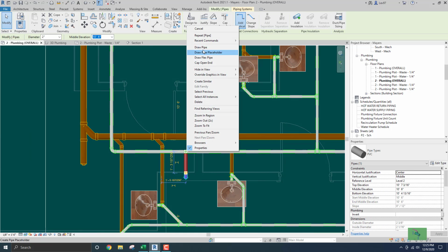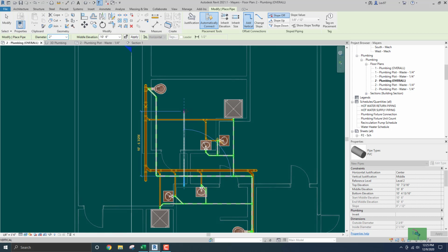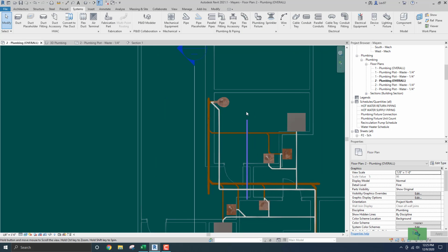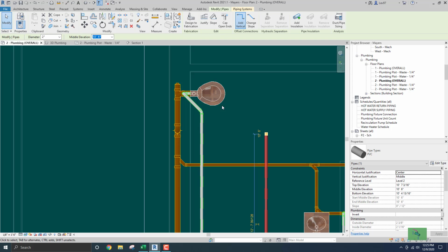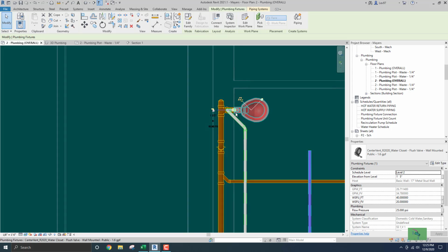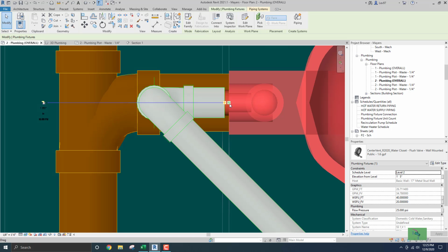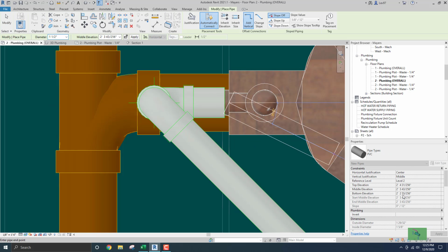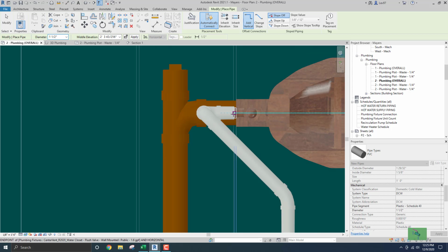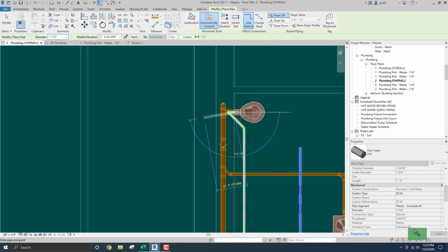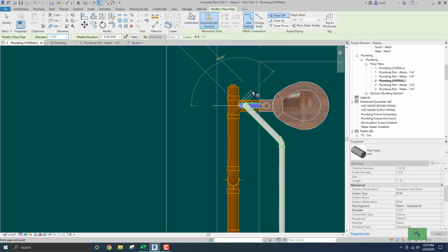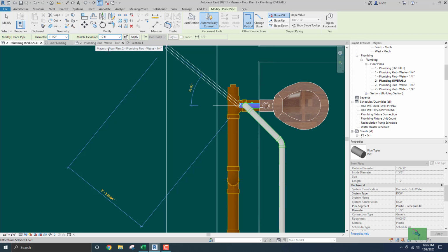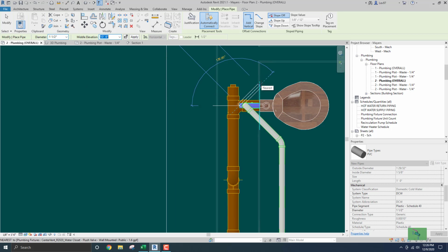Now we can go over and start to lay this out however you guys want. I'm just showing you. That's a 2" at 10'6", right? I think the cold water's there, and it's 1 1/2 inches. So from my fixture, I can come out here. Just for clarity, I'm going to come out 135 here. I've got to come out and give it an elevation, 10'6", at 135, which is 45.